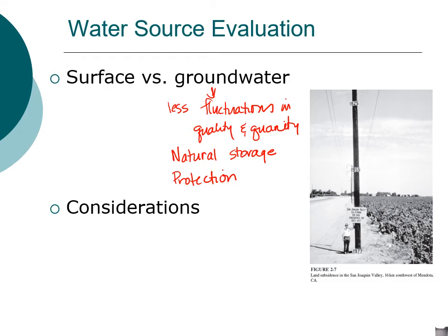your surface water. Some of the considerations that we need to think about has to be our demand. So can we produce sufficient water from either a groundwater or a surface water source? We want to prevent overpumping. So we want to avoid this. That results in subsidence, which is extremely problematic. It also is a loss of storage in your aquifer system.